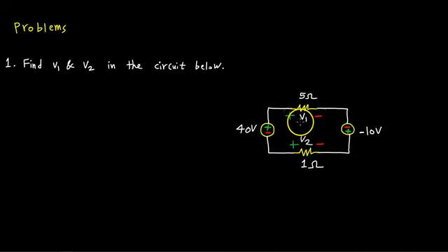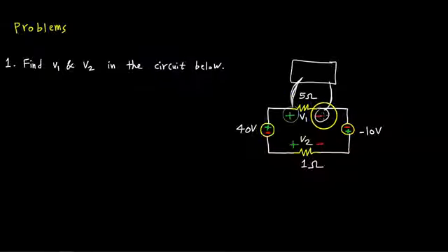With these problems, the way I like to think about them is if the polarity is determined, it's written in this manner. For example, what this is saying is, here's the plus end of the probe, either oscilloscope or multimeter, which we'll be talking about once we get to measurement equipment, or if we build the circuits and we're going to measure it, then I'm going to show you how you actually do that. But the idea is, okay, if this were a device that measured the voltage across that resistor, this would be the polarity we're using. We would be using this end, the positive end of the scope, the positive end of the probe, and the negative end in this manner.